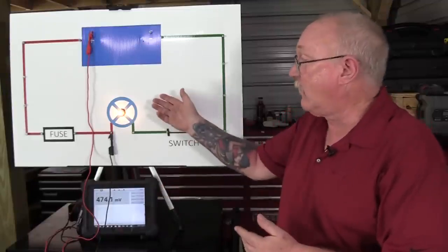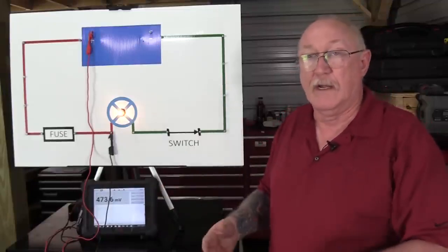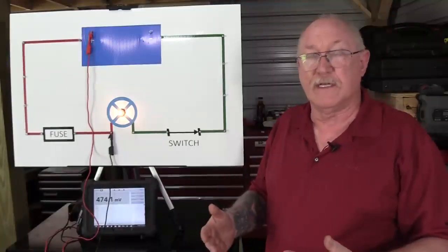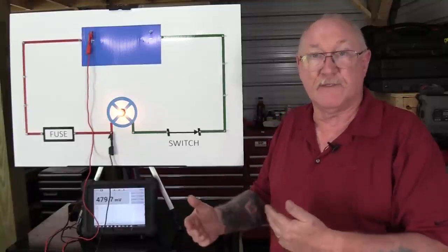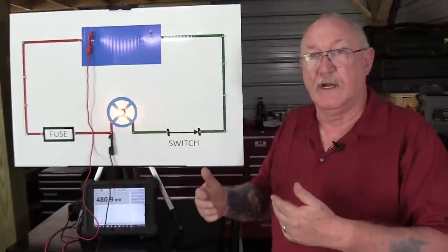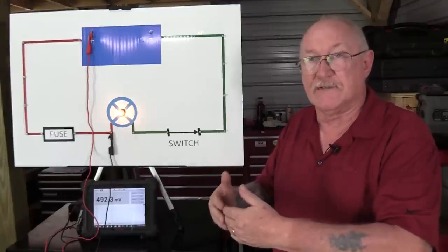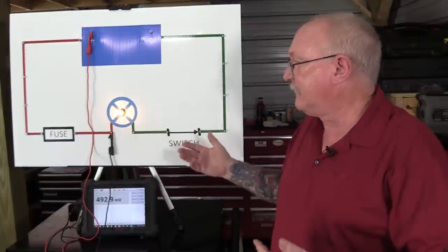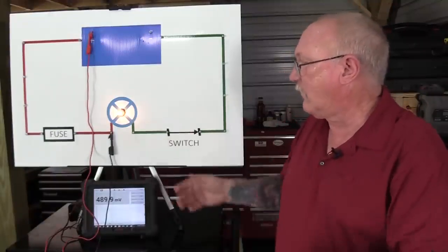The circuit has to be on. Current has to be flowing. If the circuit's not on, there's no reason to have voltage drop, because drop does what? It's actually what's causing the electrons to get pushed through that resistance, right? So that's why we have voltage drop to begin with. That's not going to happen if there's no current flow.